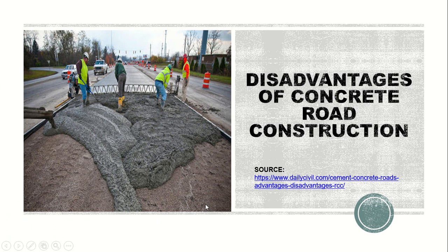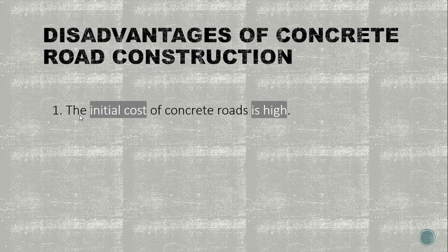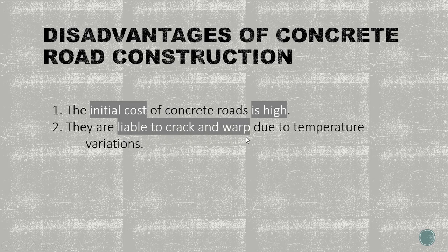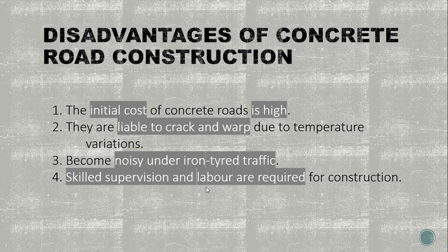The disadvantages of concrete road construction. The first one is that the initial cost of concrete road is high. They are liable to crack and warp due to temperature variations. They become noisy under iron-tired traffic. Skilled supervision and labor are required for construction.